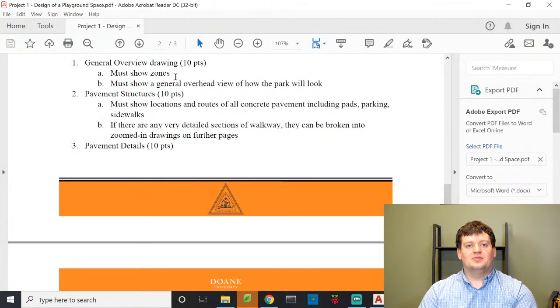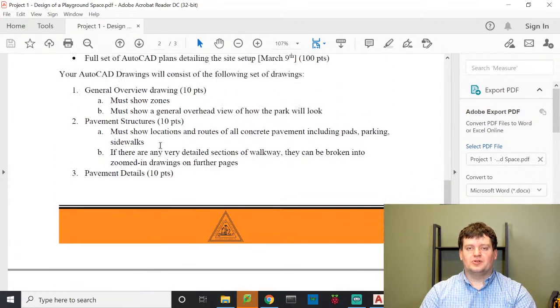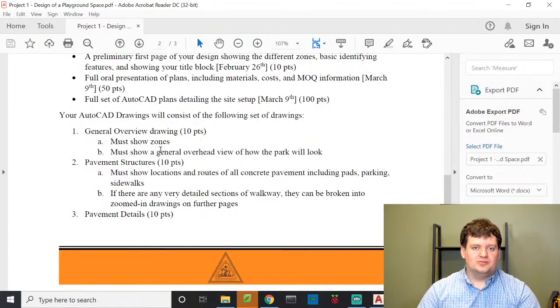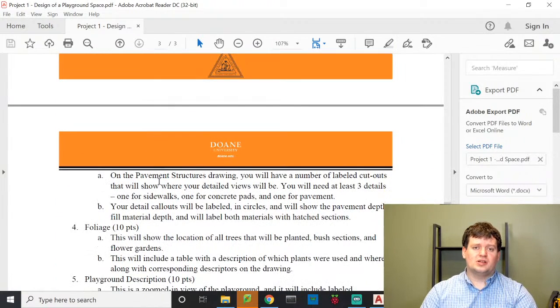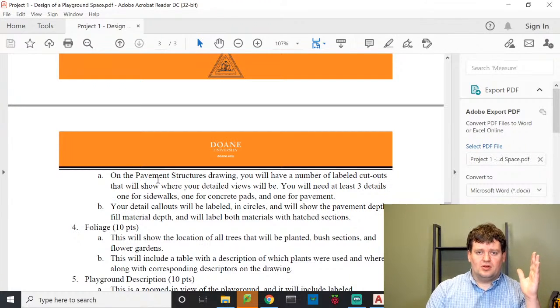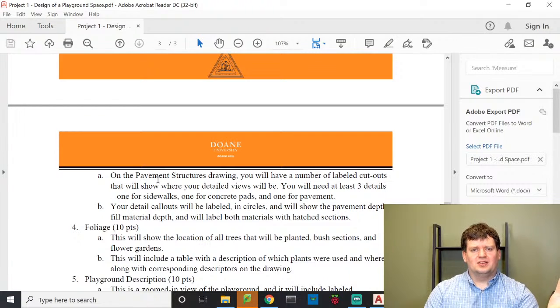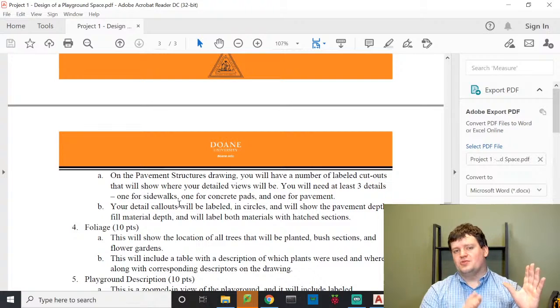But let's talk about number 3. We're going to jump into number 3 and then we'll skip back to number 2. Now, this is the way that the drawing was actually built. It should be 1, 2, 3 here. That is normal. Usually in a drawing set, your drawing set should resemble a timeline. Sometimes you draw the existing site layout. You always start with what the proposed site layout should be. That's what everybody wants to see first. Then you may move to the next page, which is the existing site layout.